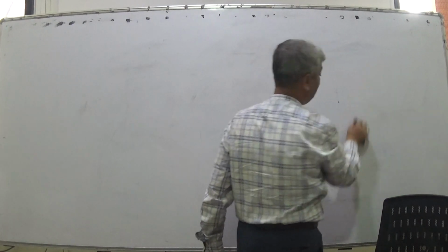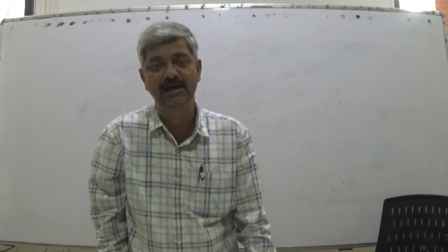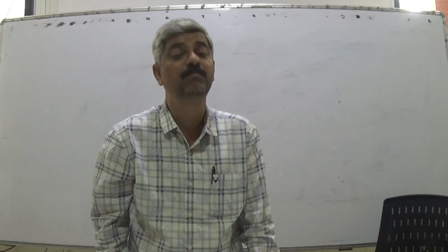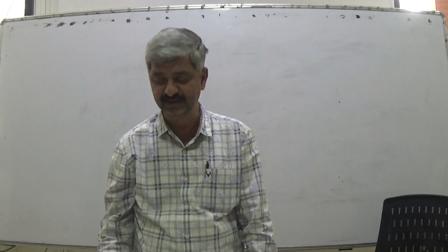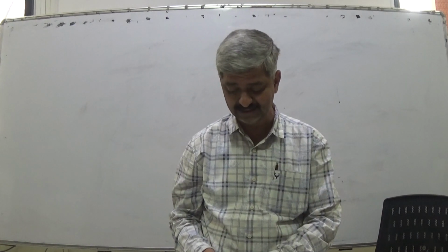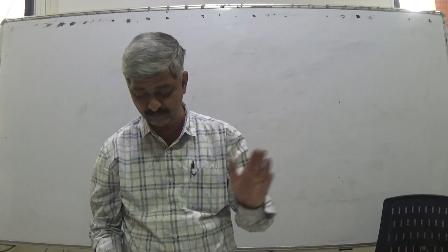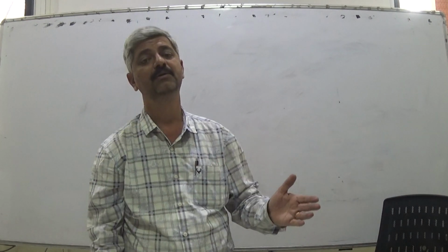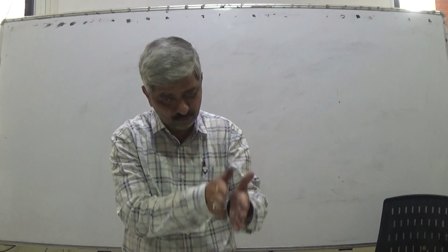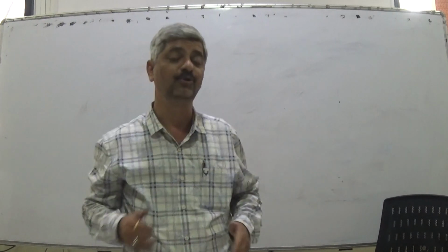This analog voltage has come from some kind of continuous variable, for example temperature, pressure, flow. In industrial automation there are many real-time variables which we need to map into their digital equivalent, to be read by the microcontroller or Arduino and used for computation to generate some results.